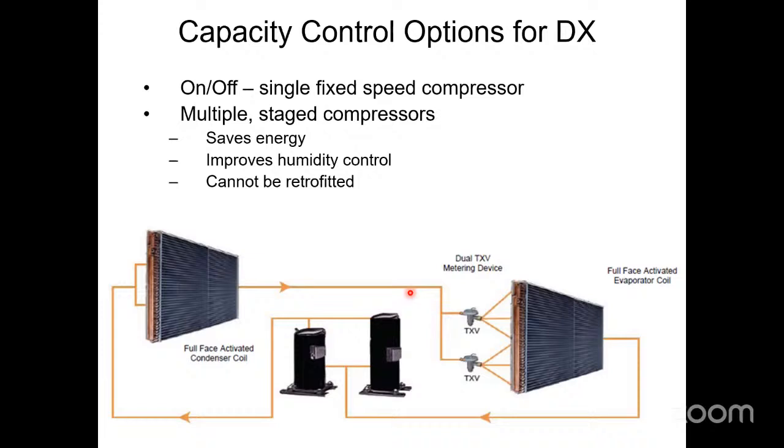It's gonna cycle on and off, which means that I'm not gonna have the coil wet all the time. That's a problem. I want the coil to be cold all the time. I want it to be below the dew point all the time because it's cold at the dew point. It does a really, really awesome job at dehumidifying. Believe it or not, it also saves a bunch of energy.